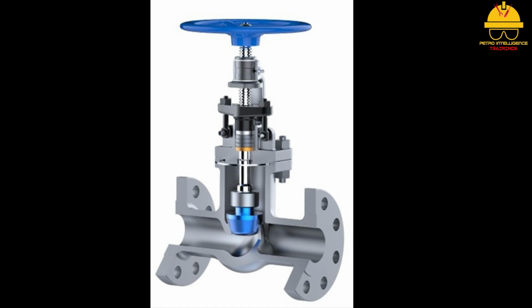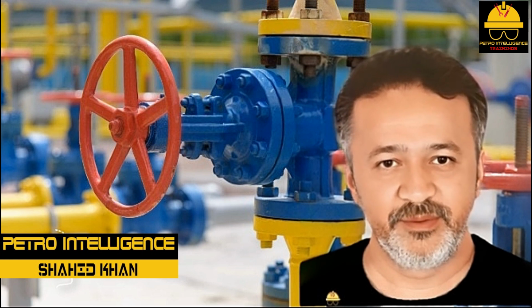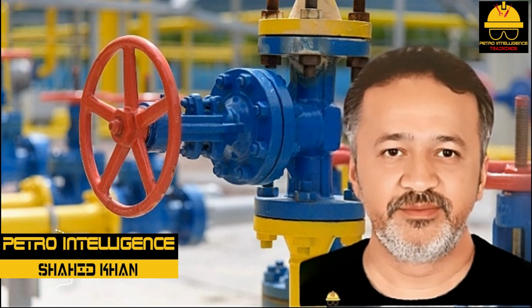Globe valves are designed to be installed in high-use areas. If a globe valve is installed in a low-use area, it tends to plug up even though it has a self-cleaning type design. Because of the 90 degrees turns in a globe valve, it cannot be unplugged with a straight rod device.